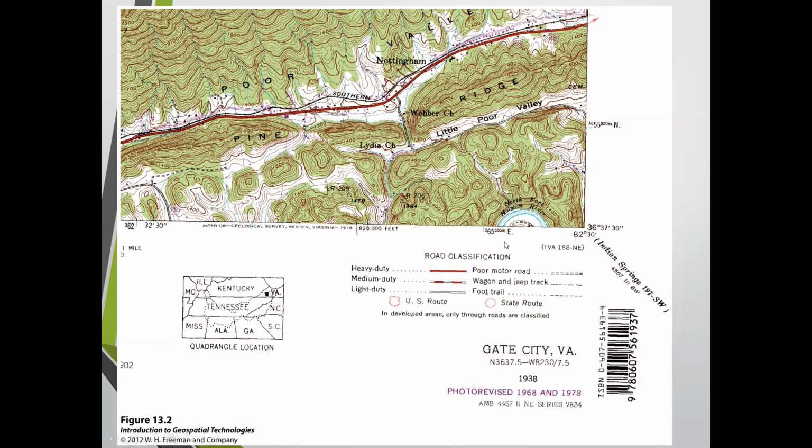You also see other coordinate systems on there, which are kind of cool. That's 65 east there, if you see that, that's I think a UTM grid tick. And then the other one over there, it looks like it's in feet. That would be a state plane coordinate grid tick. And then the other one, you got 3230. So that's telling you are at 82 degrees, 32 minutes, and 30 seconds of longitude at that point. So there was a whole lot of information on these maps. And again, that's all associated with that collar kind of stuff.